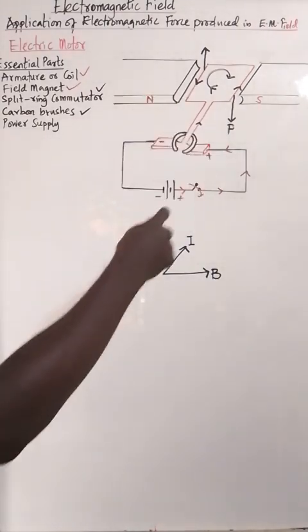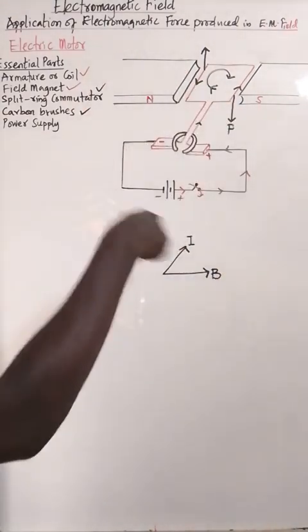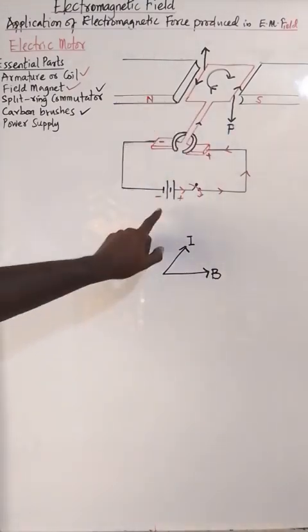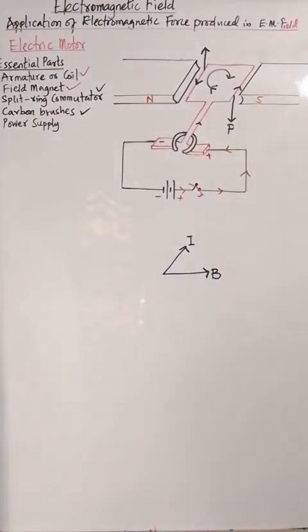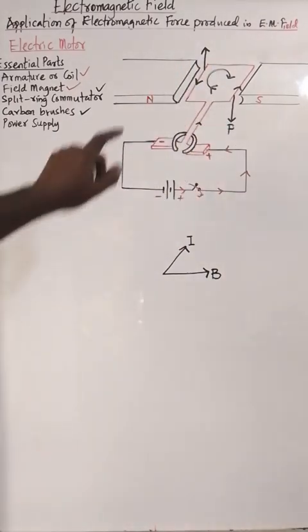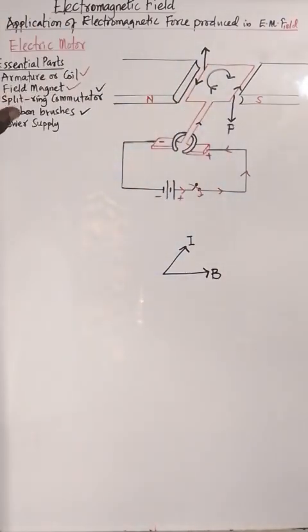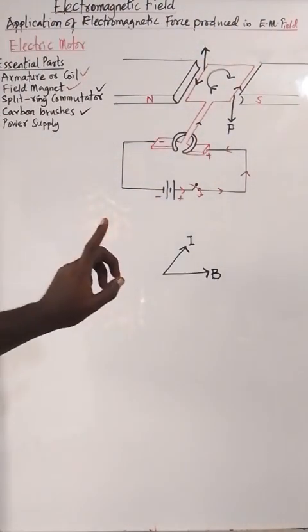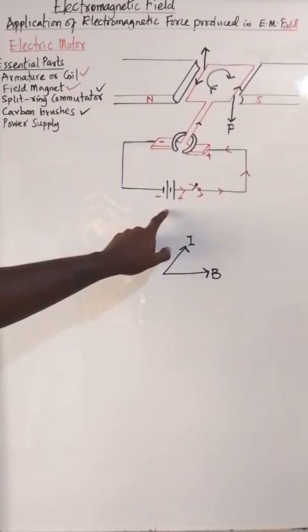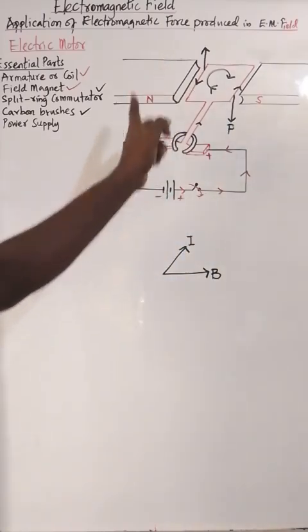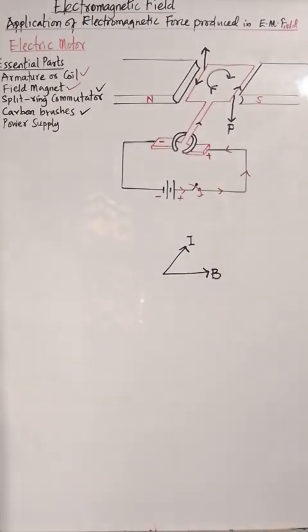So this will keep rotating, for every cycle. Now we've generated a torque from electrical energy. Mechanical energy from electrical energy is what we call a motor. If we want to rotate anti-clockwise, we could switch the north and south, but if it's already built, the north and south are fixed. So what I want to change in this case are the terminals of the cell. If you put the long one here, the short one here, the current flows this way. In that case, it will move anti-clockwise. That is a simple electric motor.